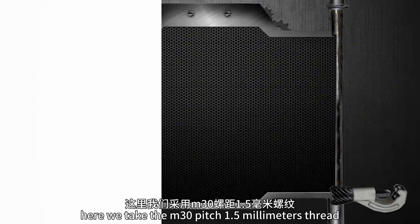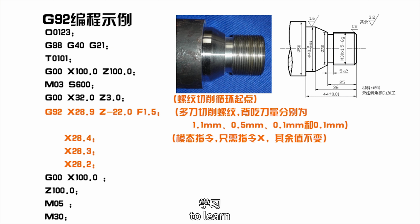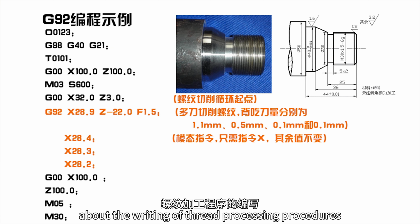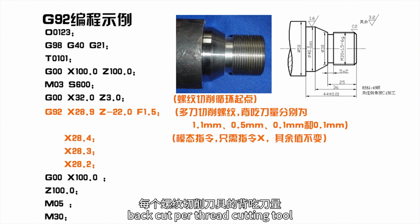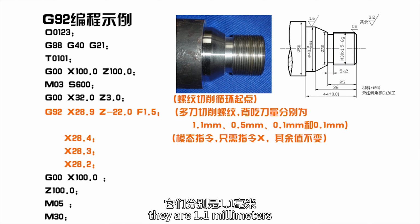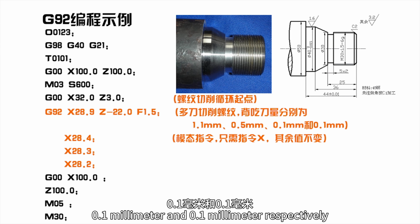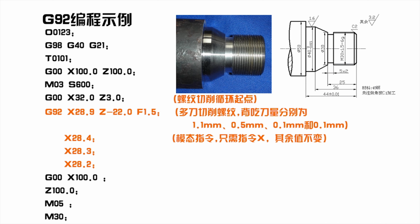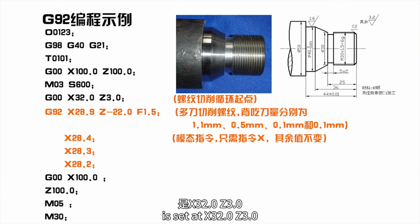Here we take an M30 thread with a pitch of 1.5 millimeters as an example to learn about writing thread processing programs. We determine the amount of back cut per thread cutting pass by thread parameter calculation. They are 1.1 millimeters, 0.5 millimeter, 0.1 millimeter, and 0.1 millimeter, respectively. The starting point of the cycle is set at X32.0, Z3.0.